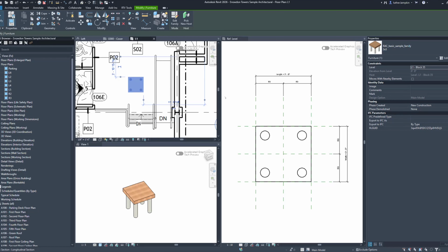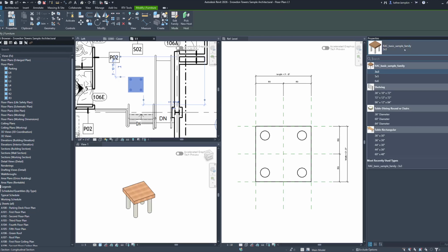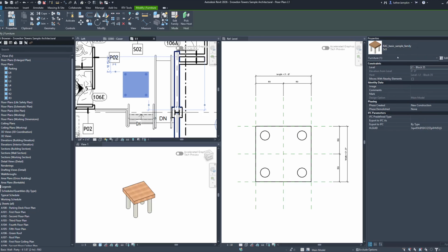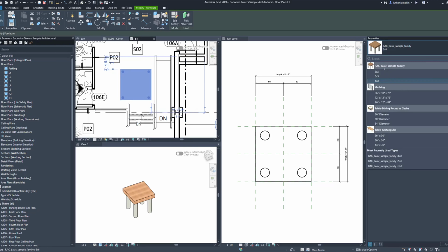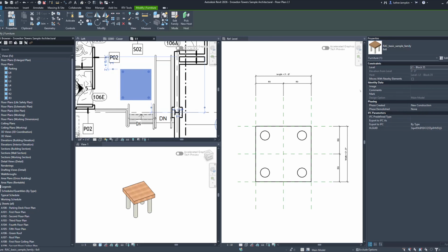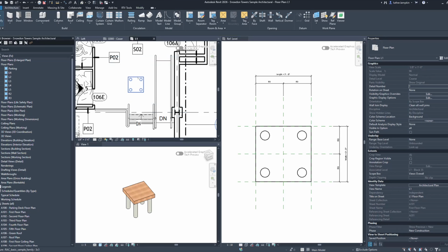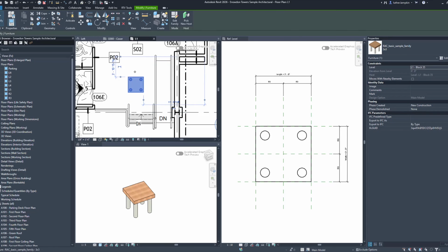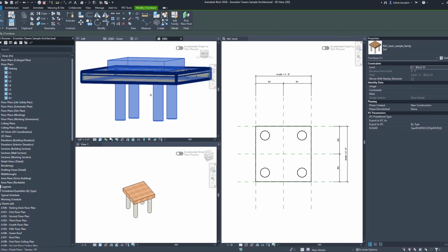If you need to, you can click on it and change it by the size. Remember the size that we created? Look at that. I'm just showing you how we create a family and the power of Revit. Here are all the other components. So what you've been able to do is create that, and if you want to see it in 3D in your project, just click on it. See this little button right here? It's called a section box, applied to whatever object you're touching, and boom.